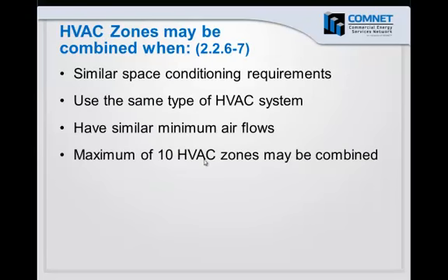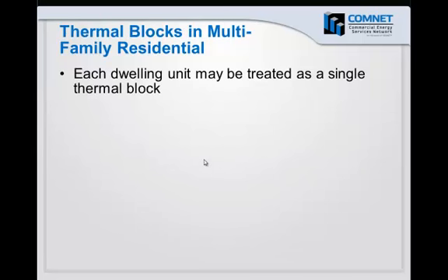And HVAC zones can be combined when they have similar space conditioning requirements, but they also need to have the same type of HVAC system and similar minimum airflows for outside air ventilation and possibly other requirements.